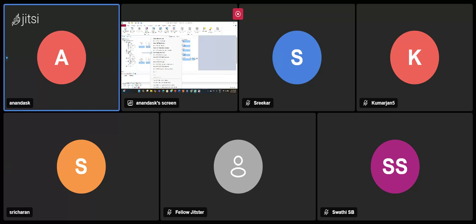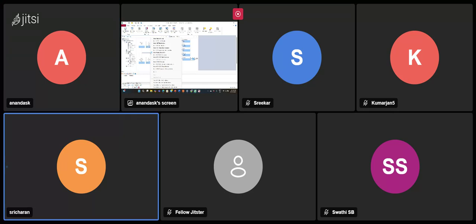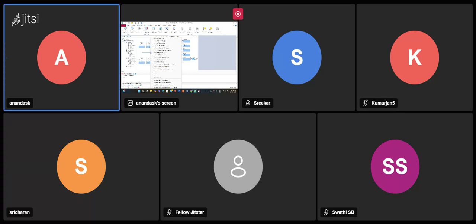We have input from the brake module, so we create this network node and simulate their signals. There we use their database and simulate the input to our node. For every particular ECU node, like BCM, we'll have a .can file; for example a PDC.can file, or for BCM modules a lights.can file. That we insert in this network node.